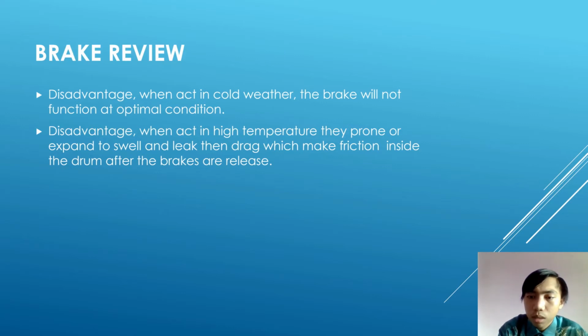So as we know, metal expands when heated. So the brake block will expand a bit. That causes the inside of the expanded tube brake to produce friction. So even when the brake is released, there is still friction, which causes the aircraft movement to not be smooth.